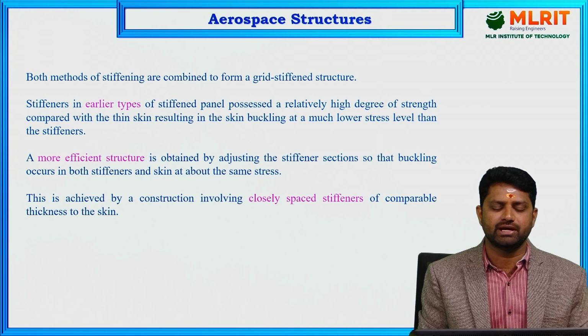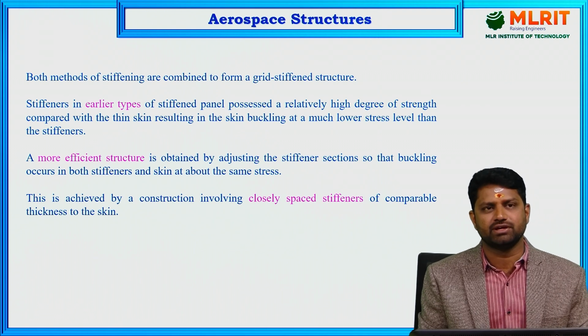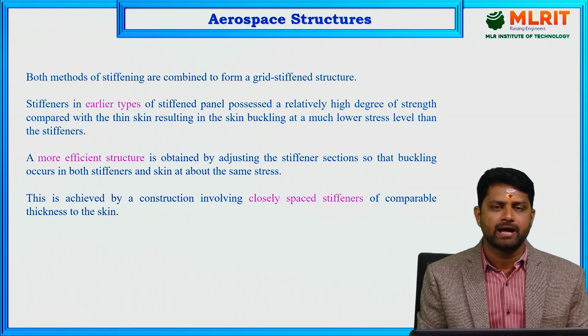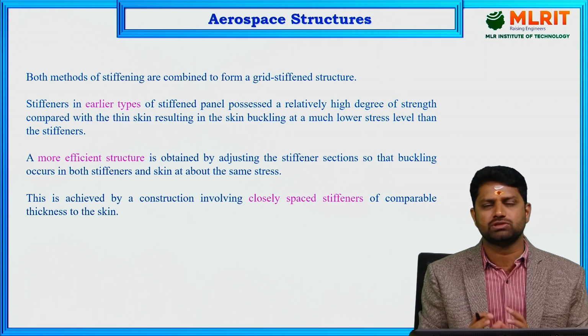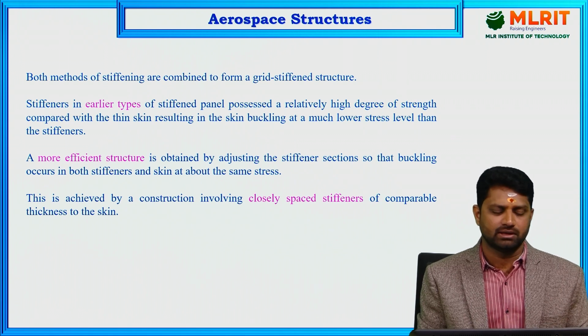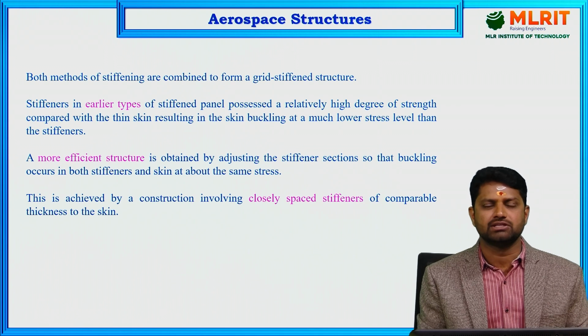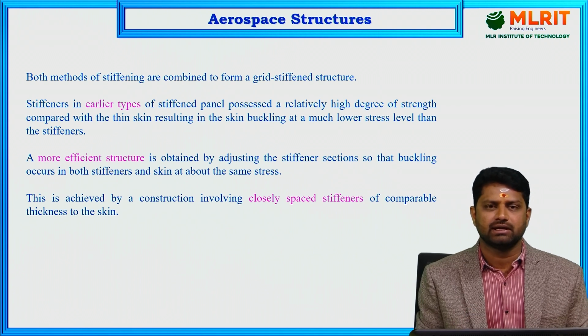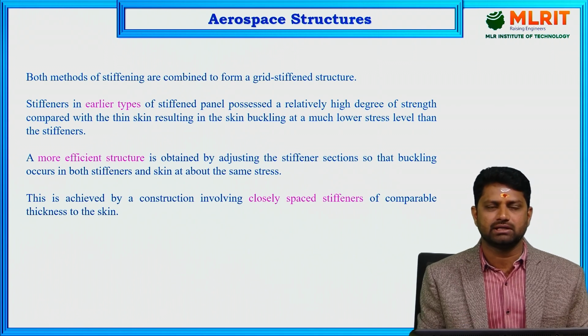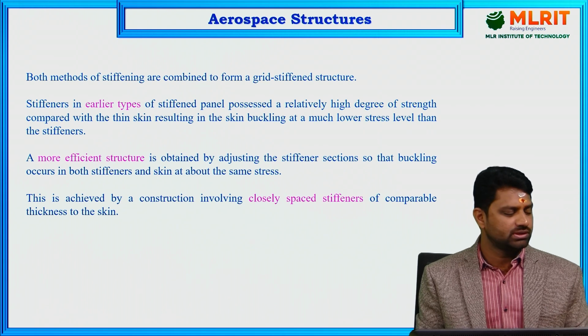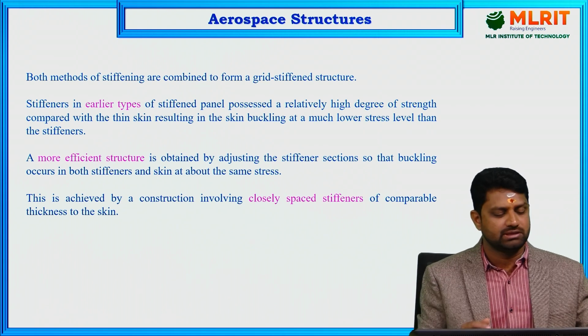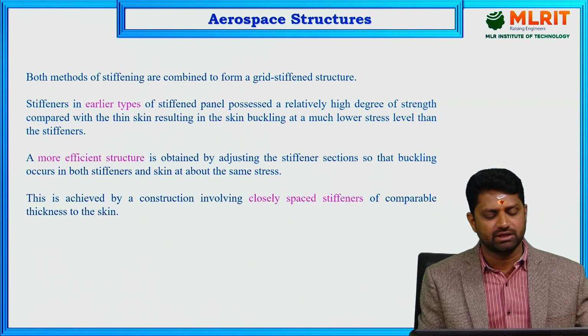This is achieved by closely spaced stiffeners of thickness comparable to the thin plate. So when you arrange the stiffeners very closely, the stiffener and skin can fail at the same stress. This is nothing but the instability of stiffened panels.